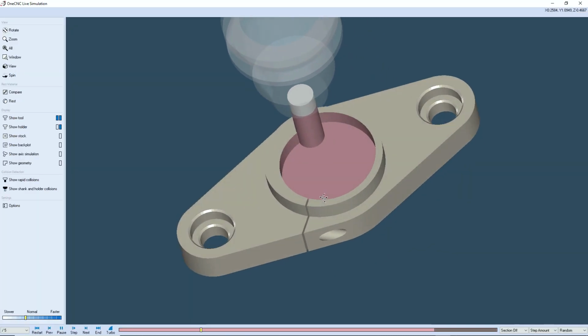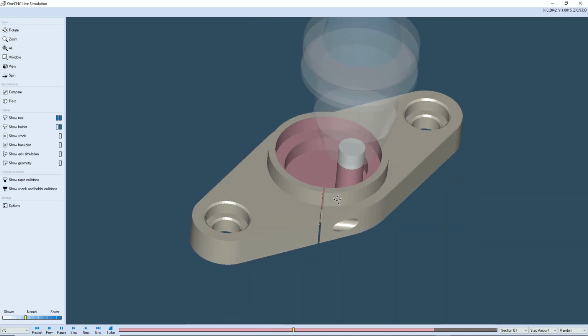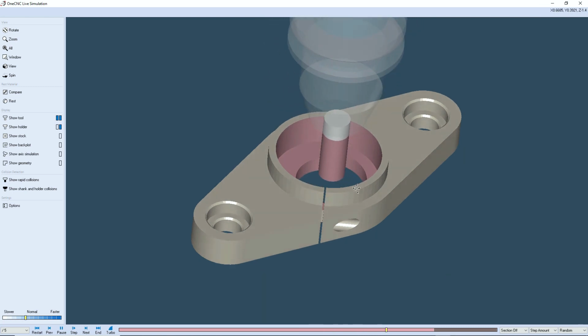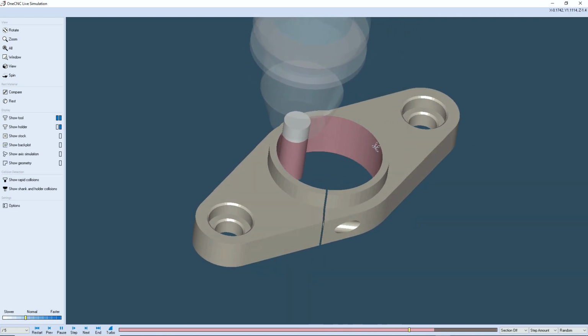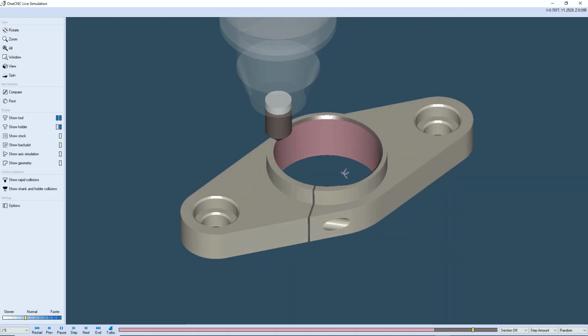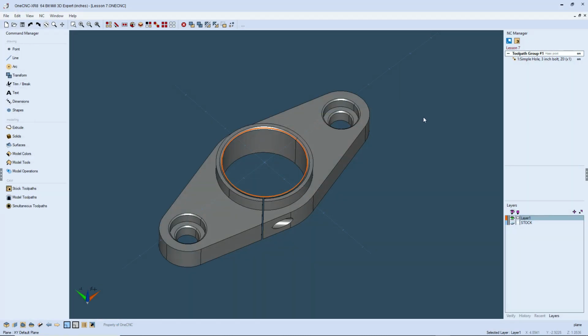All right, so what you're first seeing here is the clean circle pocket operation. And we're taking multiple depths of cut at 470 thousandths. And then that's going to finish with our chamfer operation, putting in a 75 thousandths chamfer along the top. So in summary, this lesson is to demonstrate that you can use the Hole Wizard to create a specialized pocket operation, for example, clean circle and then a chamfer, and then you could even save that as a template and use it later on.